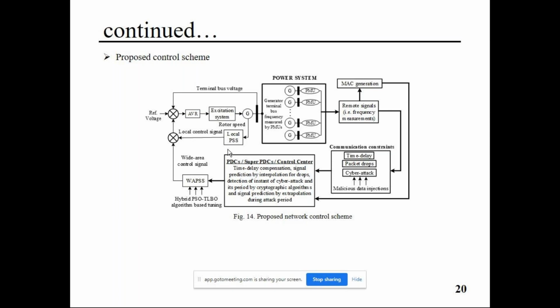So that is the planning action, but when you are at a faster time scale, the decisive action is very crucial. You cannot tolerate any mistake in the control effort, remember, the event based control effort, associated with the faster transient. For instance, you are modeling a generator subjected to the faster transient. So the direct axis and the corresponding time constant come into the picture. At the same time, the transient associated with the mechanical time constant no longer comes into the picture at that time.